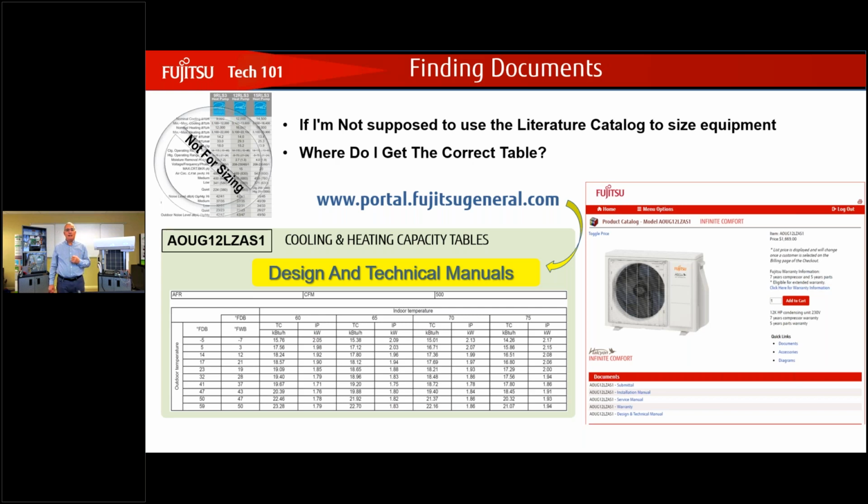We're going to hear a noisy outdoor unit, and that's a telltale sign that that minimum line set was not installed, and we will kill the compressor. And gentlemen, that is not a warranty. The minimum is not there. That compressor is not warranted.